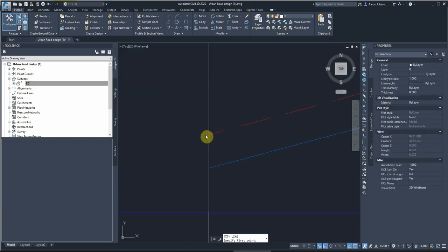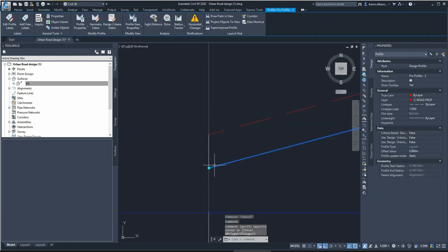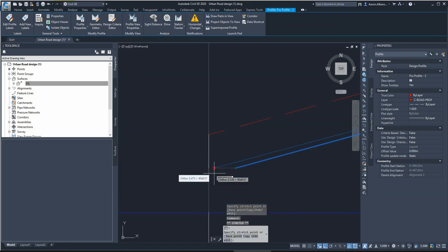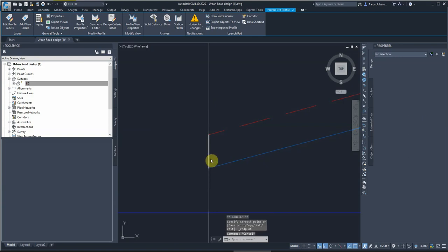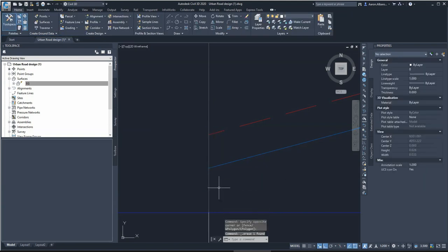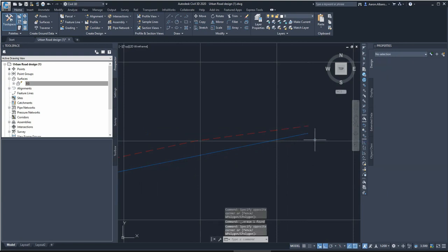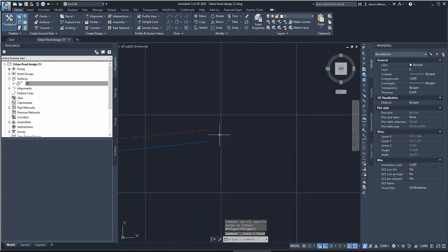I draw a vertical line here, up to here, then go back, space that way, and go back, shift right click in point of this line, and that will fix to it. I can delete this line or keep it, it wouldn't matter really. Okay, I have to check the same thing for the first profile.